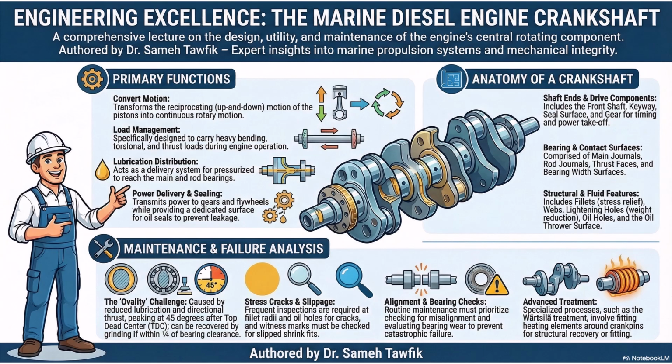We looked at the inherent contradictions of a component that must carry brutal torsional and bending loads while simultaneously acting as a delicate, pressurized fluid delivery system. We decoded the forensics of failure, understanding how stress concentrators at fillet radii and the sheer vector force of a connecting rod at 45 degrees past TDC can pound hardened steel out of round. And finally, we saw how even the most massive multi-ton marine components still rely on the precise physical application of thermal dynamics by human hands. It's a testament to the incredible sophistication hidden inside the machinery that powers the industrial world. I think this knowledge changes the way you'll think about the everyday machines operating all around us.